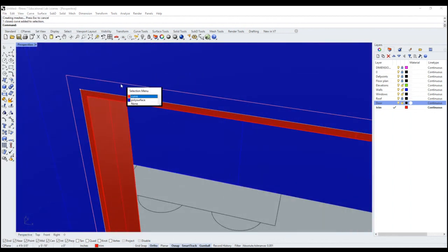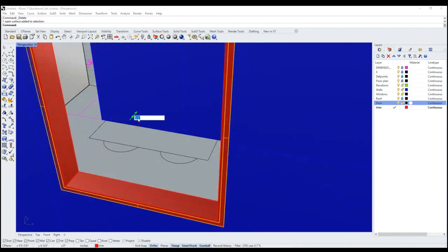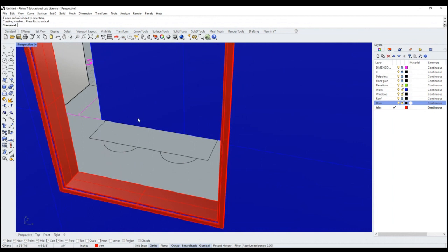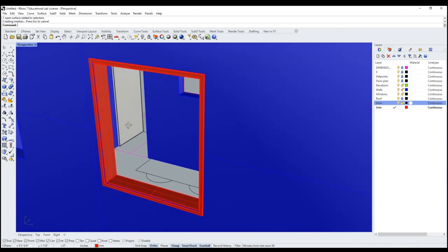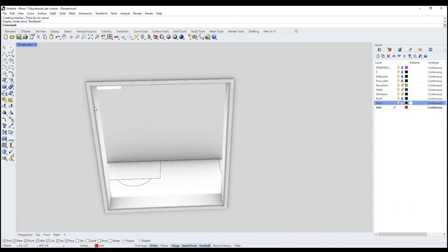We're going to select this curve, planar surface it, and then delete the curves, take the surface, and then we're going to go negative 1/2 inch because our arrow was faced the other way, but it doesn't affect the window.